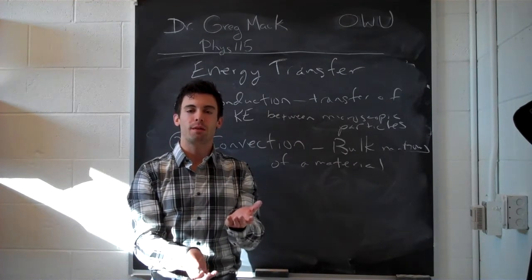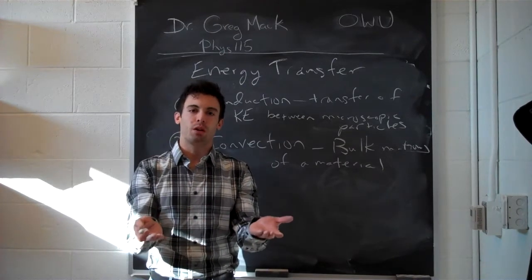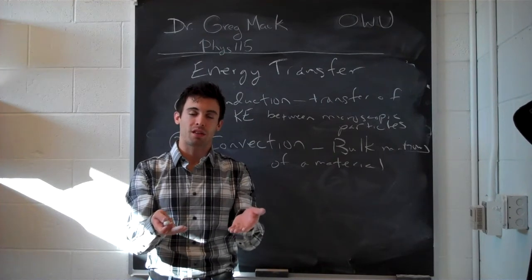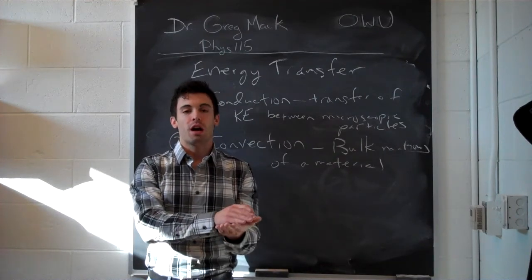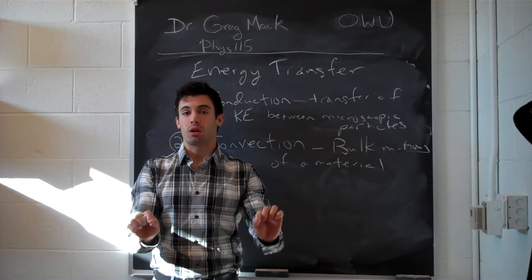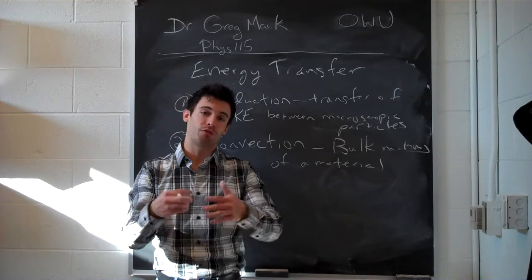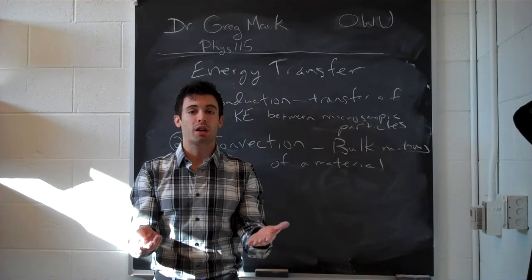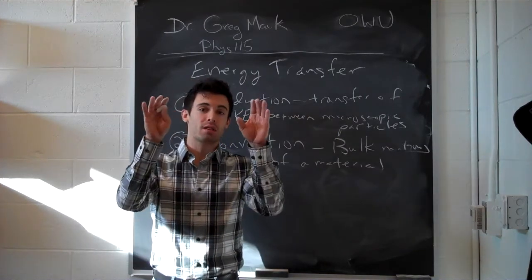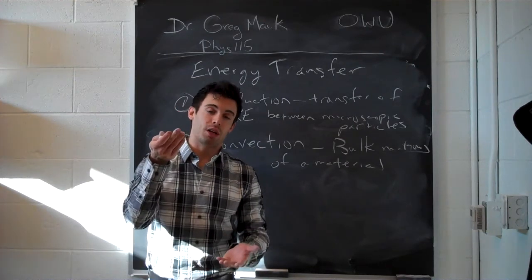Okay, so the heat is impacting the bottom of your metal pot, and that bottom is in contact with the water. So you have a bit of a conduction process happening right there, where you have the hot metal surface that is then touching that bottom layer of water. So that bottom layer of water gets heated up. So what happens with a fluid like that, when it gets hotter, its density decreases, which means that it will start to rise, because that's what happens with a lower density in a material. The lower density will rise to the top because it will float.